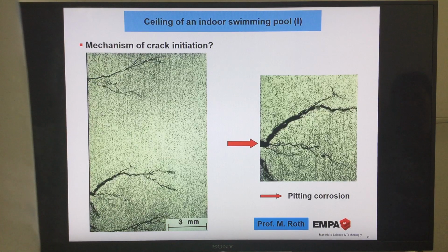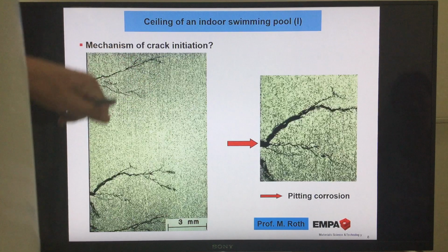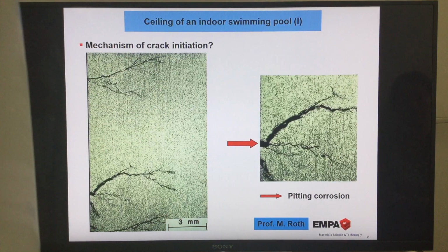What is the composition of this layer? And you think, of course, of the composition of the stainless steel. What did we say? It's a chromium-nickel steel. So it's mainly chromium. The purpose of chromium is first to make the hardening inside of the material, solid solution hardening. And secondly, that the chromium is used for this protective layer, and the composition of this layer is Cr2O3, chromium oxide. It's a very, very thin layer, but it's very efficient, it's self-protecting.